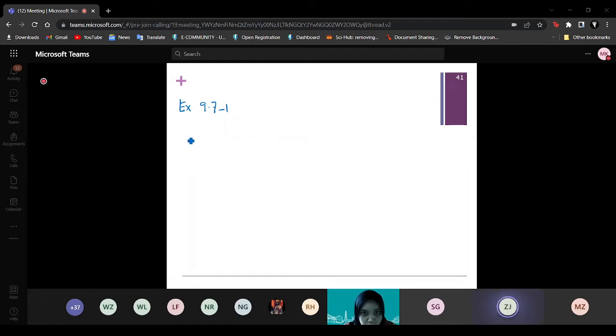In the falling rate period, they have all the data. And then what happens is that they build up a graph of 1 over R versus X, and they can plot it. This is only in the falling period, all falling points, and then they find 1 over R here.